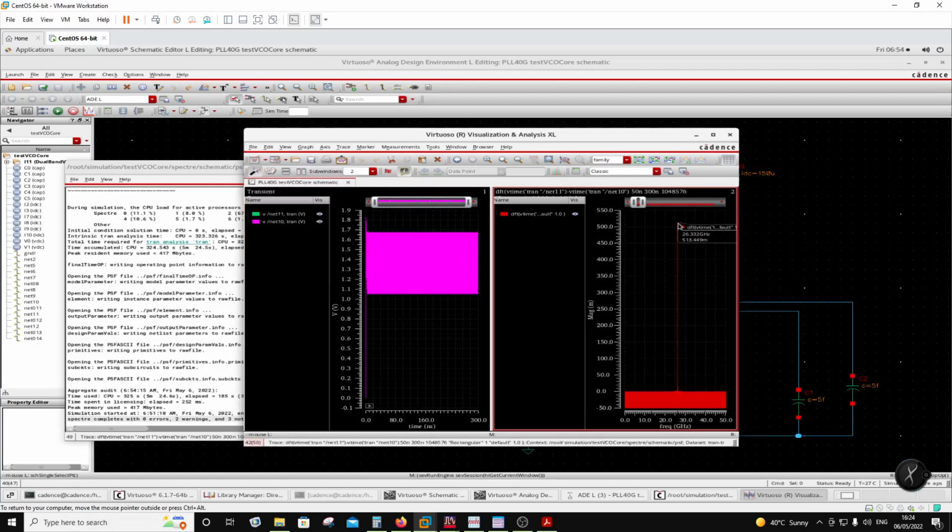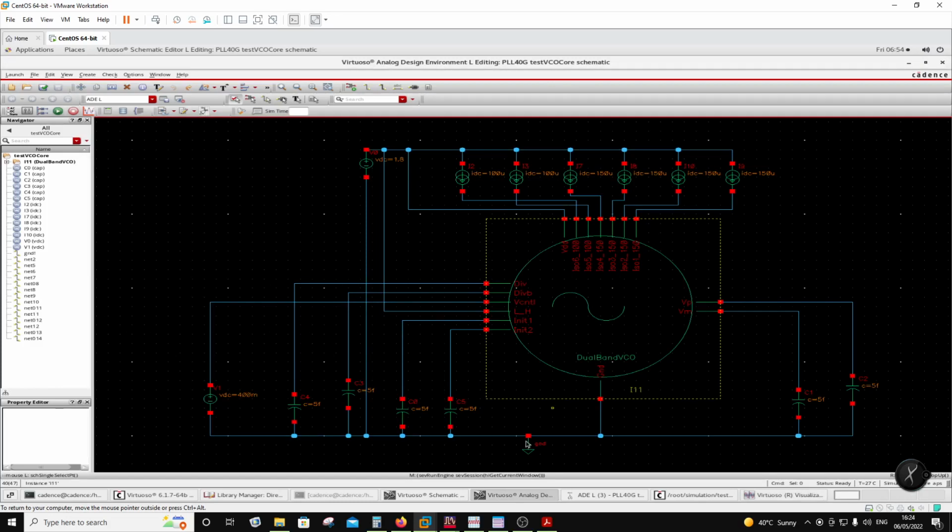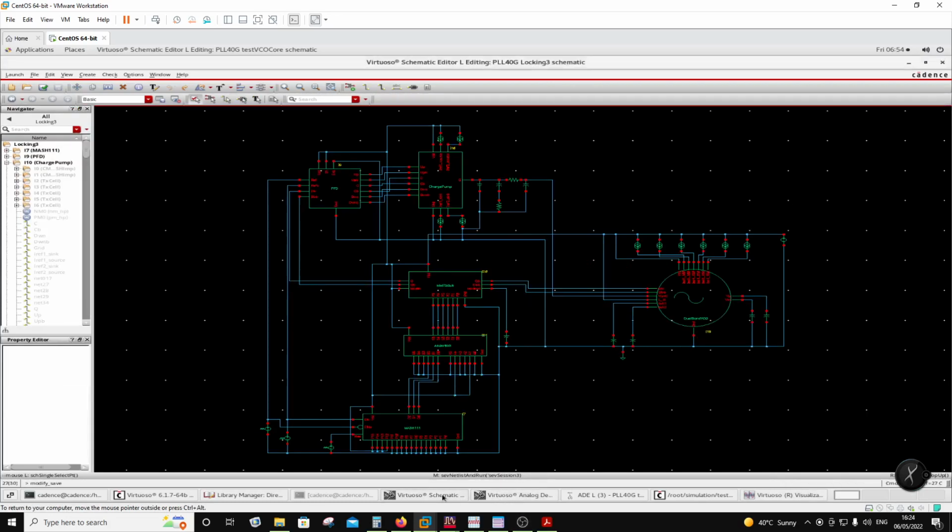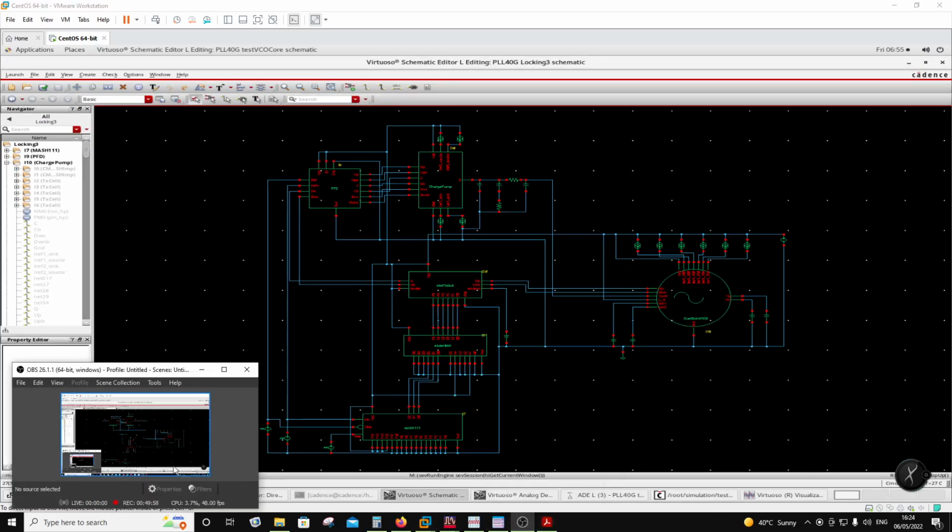Okay, so now here this is 26.33. I have covered the lower band as well as the high band. The lower band was from 24.37 to 26.4, and this is going from 26.33 to 28.55. So basically the entire band of 24.37 to 28.55 is covered by this PLL, and this is a dual band fractional-N. Okay, fine. So I'm going to stop here. Thanks a lot. Thanks.